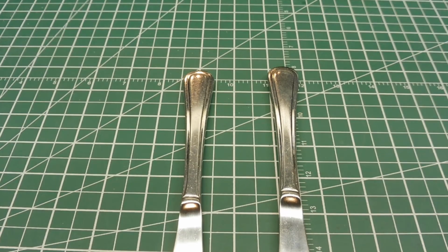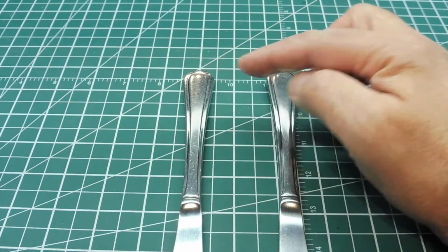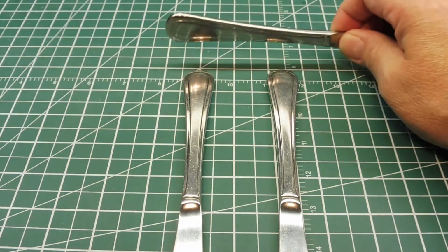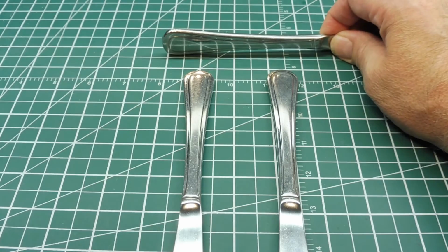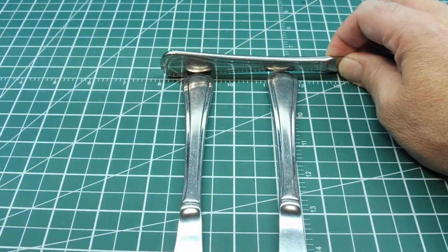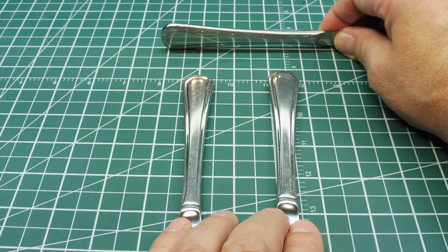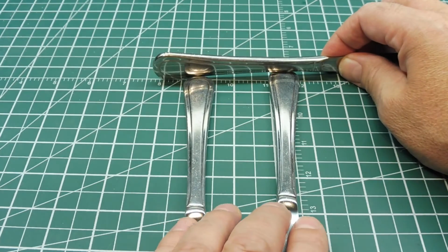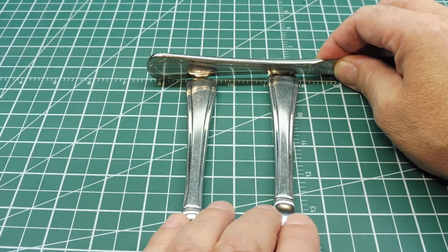Okay, here's a crude model of a push button switch. Here are the two contacts inside the switch, and these would be the terminals leaving the switch where you hook up your wires, and this would be your shorting mechanism. So in this position, the push button switch is open, and in this position it would be closed, and you would have current running through the switch. What happens in slow motion when you depress the push button switch, you would get contact bounce. You would get bouncing action like that. And the duration of the bounce is about 10 milliseconds before it settles down, depending on the type of switch.